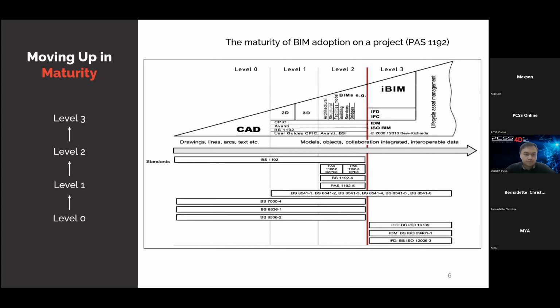Another common practice when you're doing a BIM level 2 project is you need to have a common data environment, also known as CDE, where files are stored centrally, and files are federated, kept, reviewed and coordinated in this common data environment. Nowadays it is normally in the cloud. Okay, so this is the ideal one. This is the best, and this is what we should aim for, because if you can do level 2, then your BIM horizon expands.